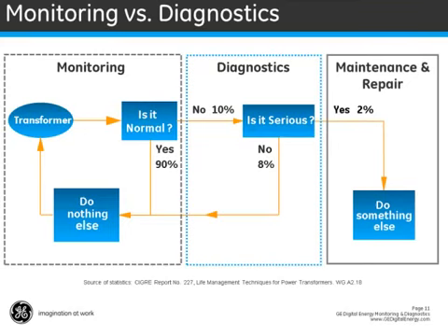If we were to rely only on DGA technique alone, then the question would have to be, how often should a DGA be performed to guarantee maximum transformer protection? The answer is not that simple. For maximum protection, what would make the most sense would be to do a DGA more often than the fastest evolving transformer failure mode.